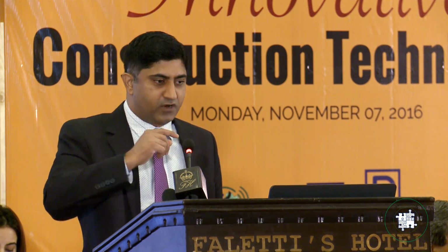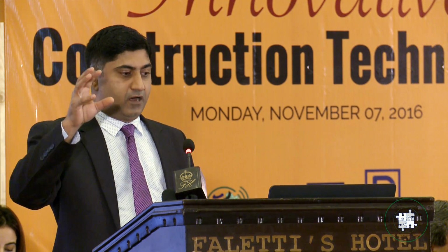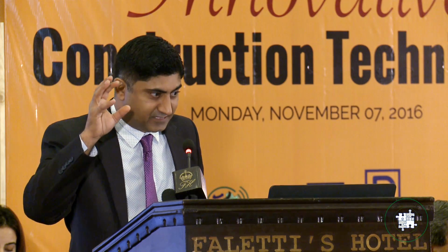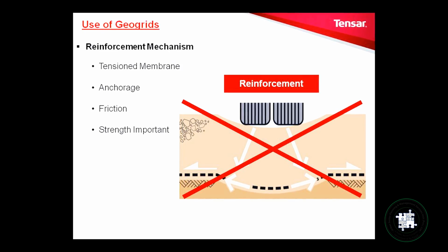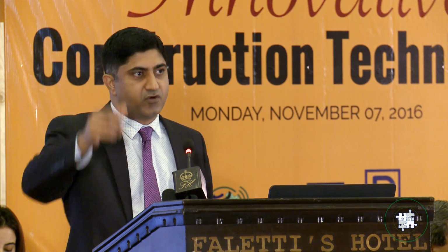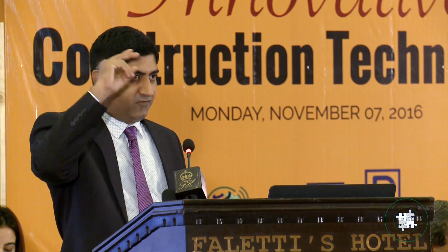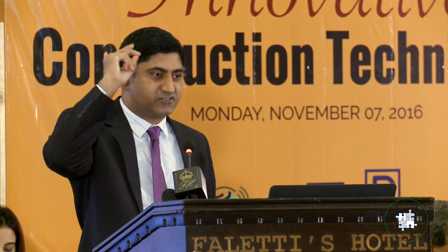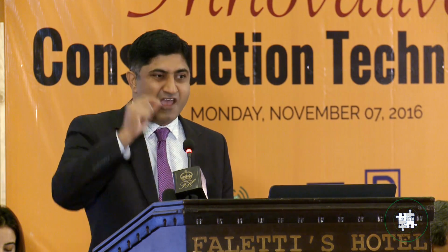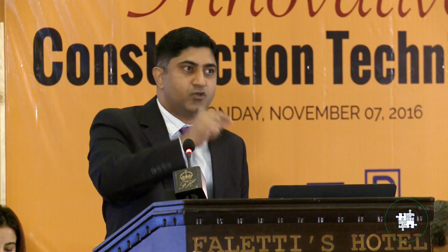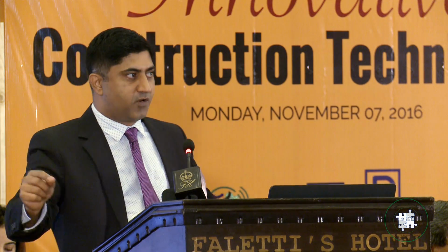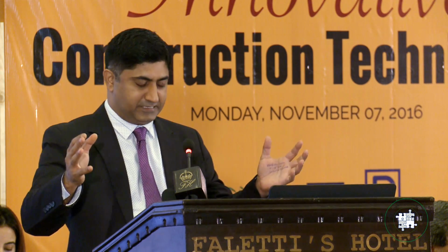I mentioned before, there is another function that is called the reinforcement mechanism. This time we are talking about pavement structures, not reinforced soil walls. That is different. Within the pavement layer, we have two distinct functions: one is stabilization, one is reinforcement. Stabilizing geo-grids perform, and reinforcement geo-grids perform, when incorporated into the pavement layers.